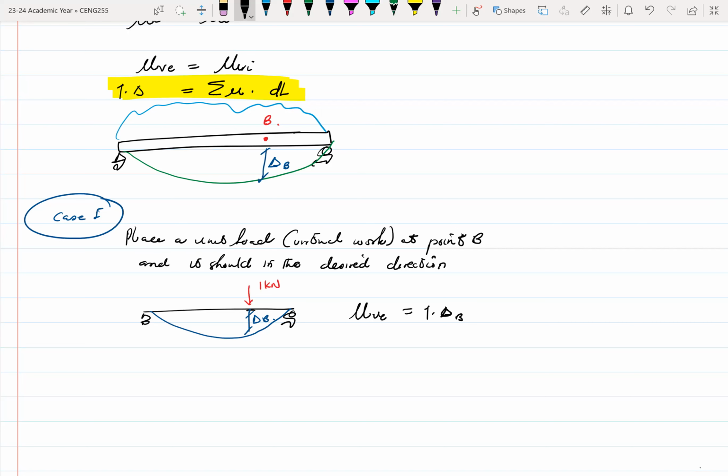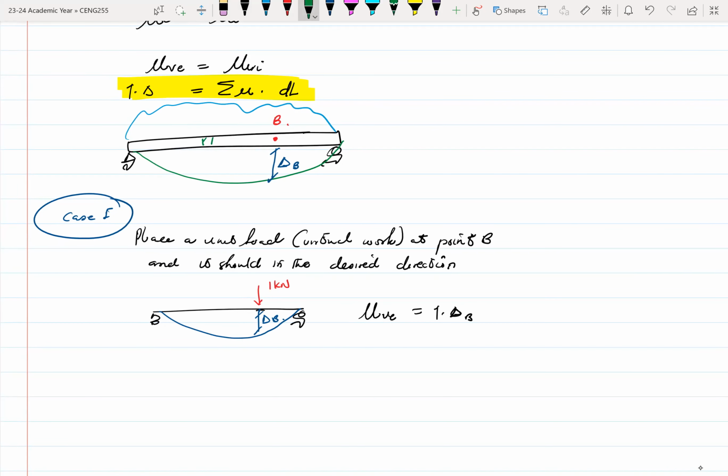All right. So for us to understand the internal behavior, we just take a small element of the beam and then try to expand on that. So let's take an infinitesimal element of the beam. Its width is dx, right? Let's say from point A to where the small element starts, I don't want to overcrowd myself, let's call that distance x. It can be anywhere, all right? And the width of that is dx.